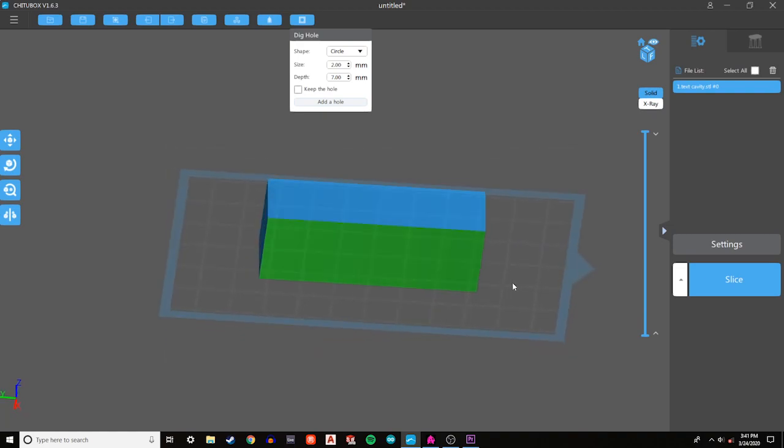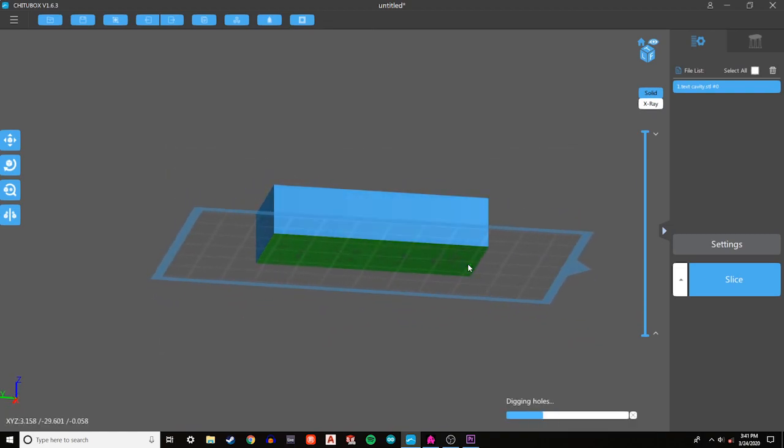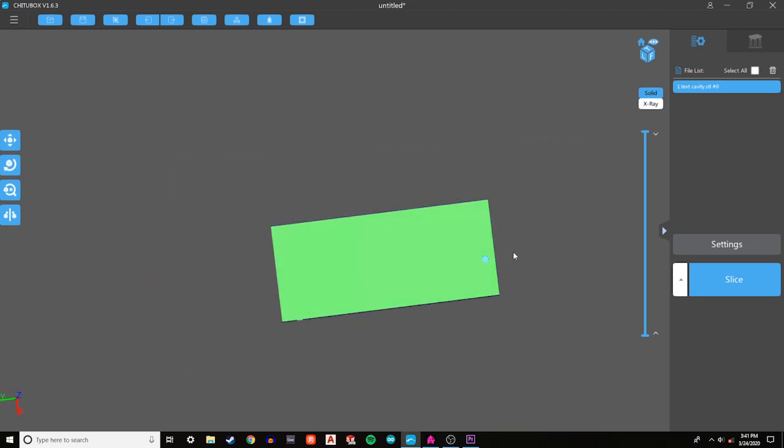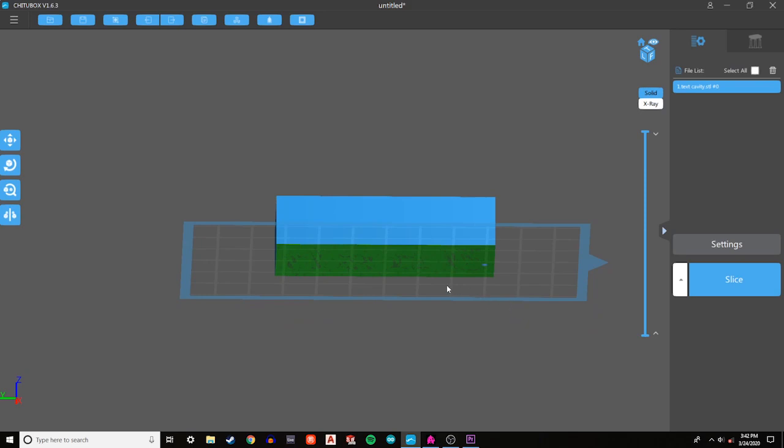So I'm going to try and just angle it so we can see that shading like we did before. See, and there you have it. That's our first hole. That's going to be a nice sized drainage hole. Hopefully that will help us out a lot, because I think when you see later my actual part, you're going to see where some of the liquid is actually still in the cavities and it's not coming out very well because the holes I used were just too small. So I want you guys to be able to avoid that if you can.